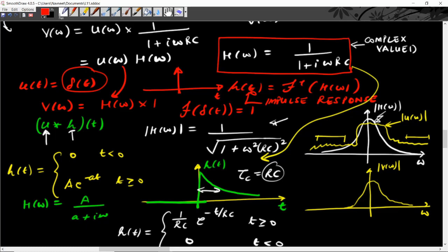So the filters that we have discussed in this lecture are low-pass filters, but similarly you can design filters which allow high frequencies to pass through while they remove low frequencies. Such filters are called high-pass filters. Or you can keep frequencies in a certain band to be unchanged while removing all other frequencies, and such filters are called band-pass filters. So these different type of filters can be designed simply by using the transfer function h of omega, so that the frequencies that are unwanted are zeroed out by multiplication in the frequency domain. And some of these high pass and band pass filters we look at in the next lecture.